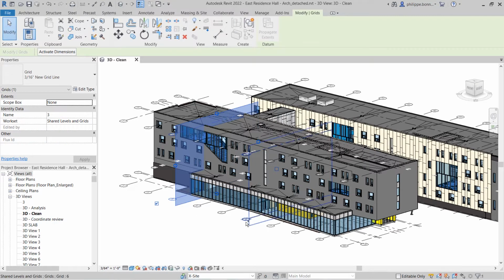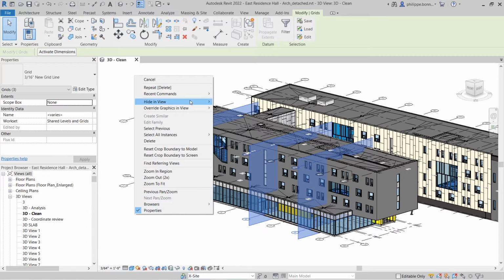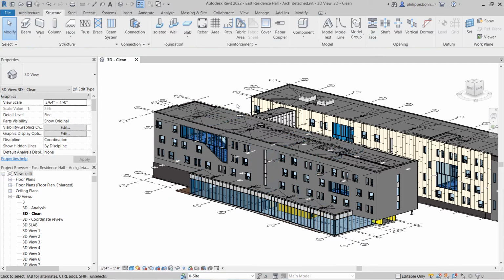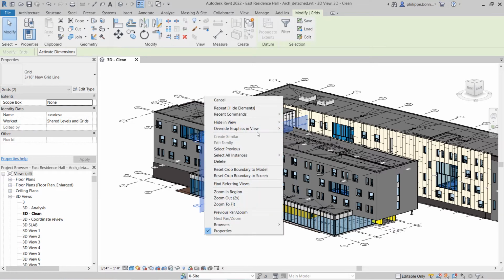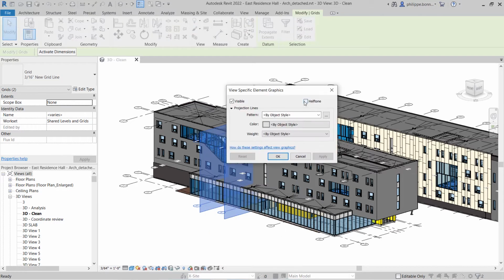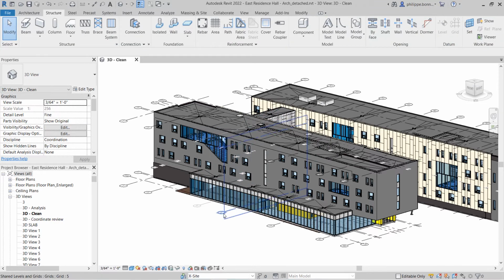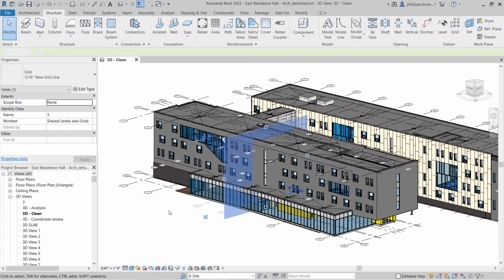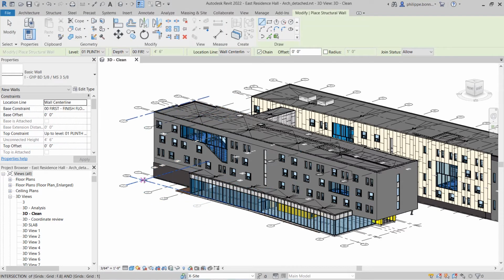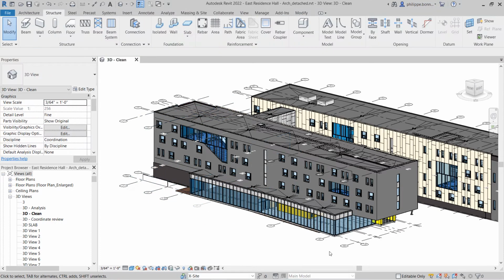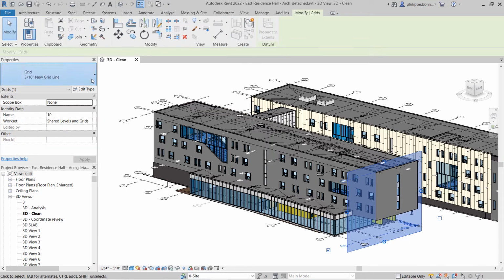In a 3D view, you can treat grids in many of the same ways as in a 2D view. For example, you can hide grids by element, category, or filter, or by using the Visibility Graphics Overrides dialog. You can display grids using halftone. You can copy, cut and paste, or delete grids from the model. You can snap to grids when placing other elements. You can change grid instance and type properties.